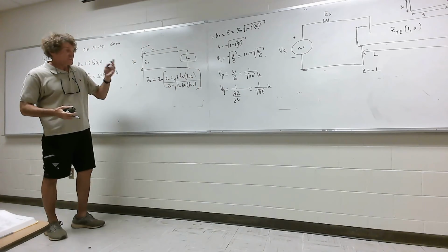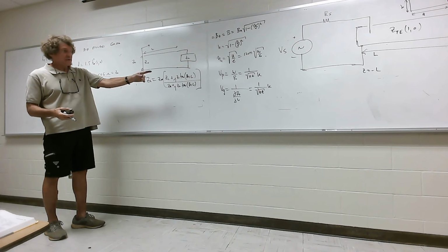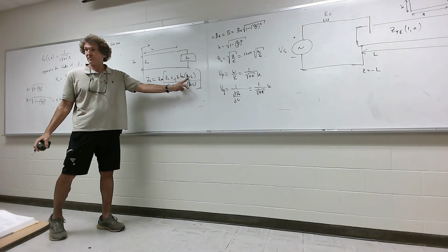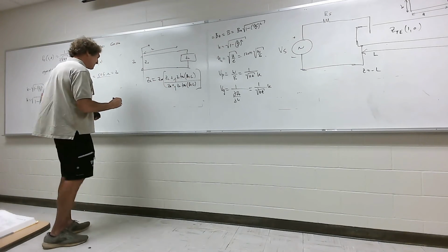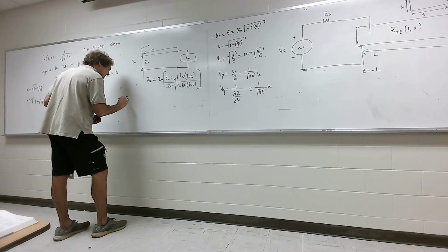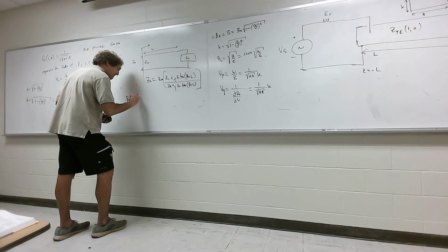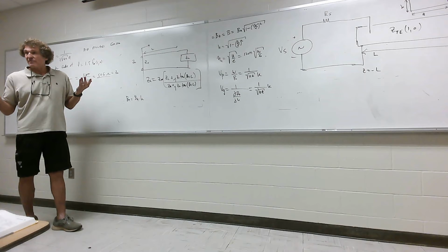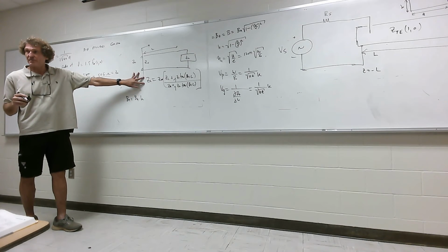Now, I didn't give you a ZL. I can do that in a second if you want. But beta Z is the critical thing. This is not beta per se. It's beta Z, beta along the guide. And beta Z is equal to beta unguided times K. Do you follow me on that? Now, L is whatever L is in meters, but this will give you the input impedance to that guide. You remember doing this stuff for transmission lines?